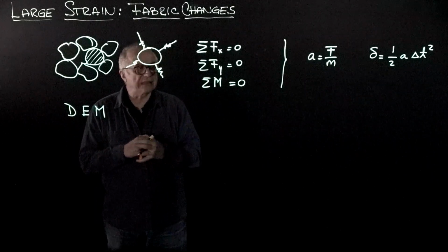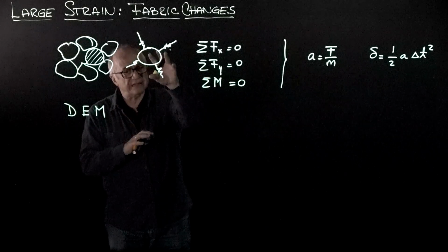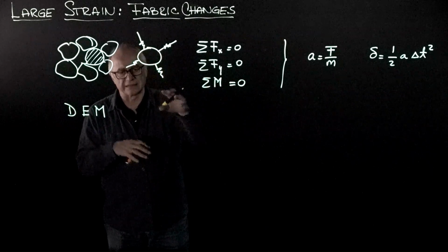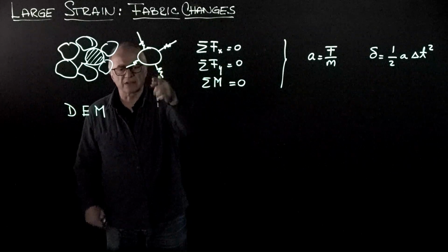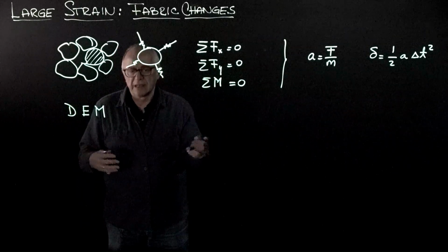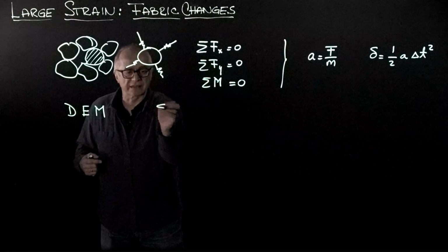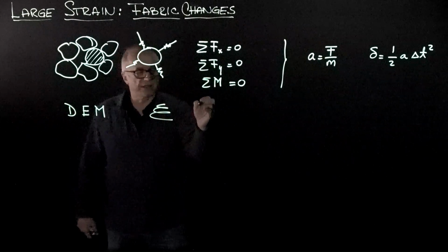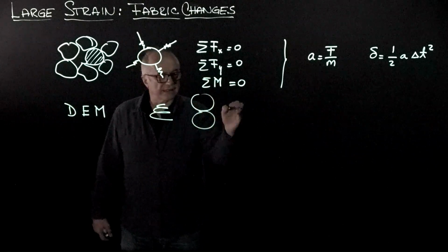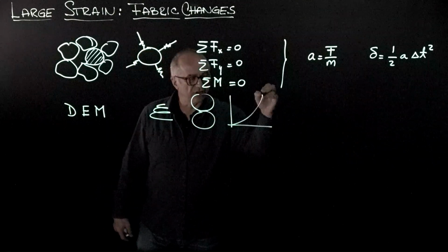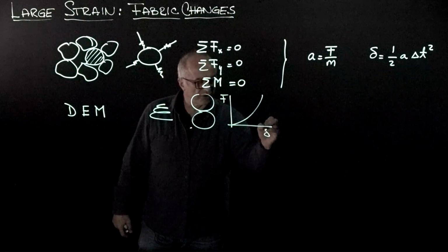What is unique about particle scale analysis in the context of soils is that the interaction between particles is going to happen through springs, and those springs could be, for example, nonlinear springs, because there is a Hertzian contact that, as you may remember, is a nonlinear force deformation.